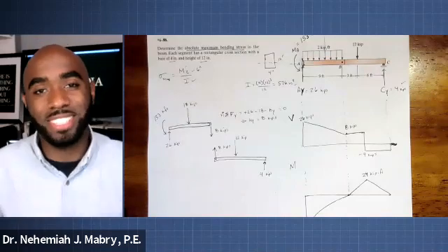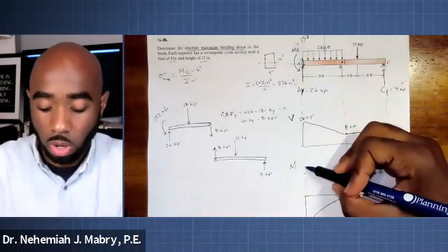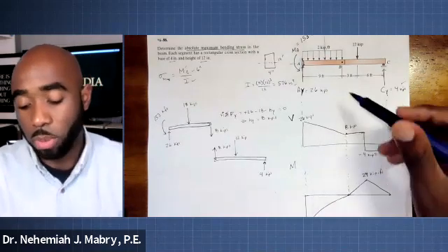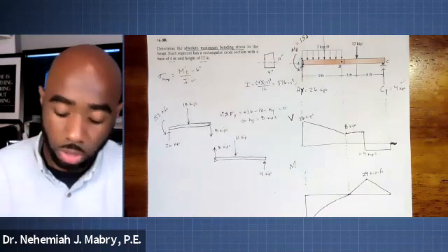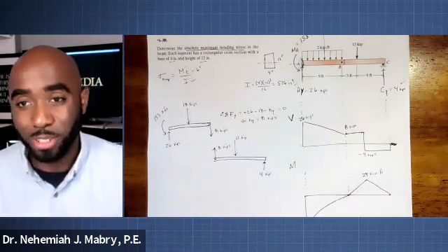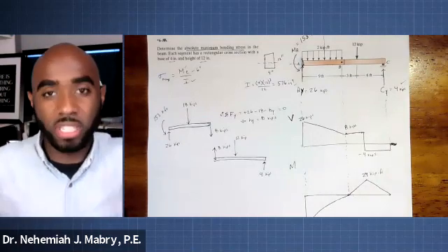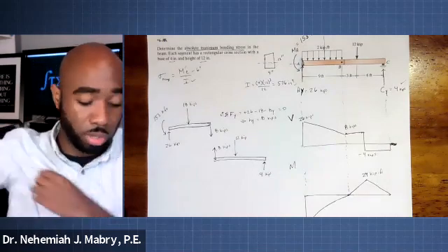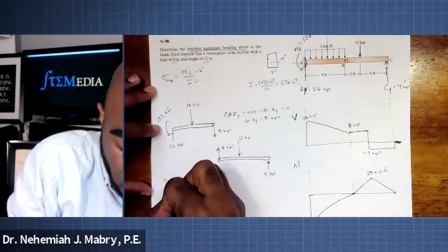Practice these. You can definitely get used to doing this, and it can start flowing for you. But again, you remember these clues. When it's a hinge, you know that your moment is going to be 0 there. You know that the value that you're going up or down is going to be equal to the area under the shear curve. All these connections are really helpful when it comes to drawing these things. But with that said, let's get right to the home stretch.